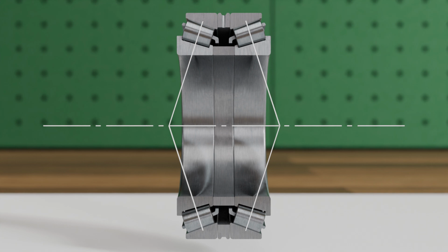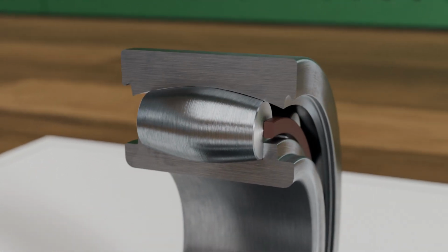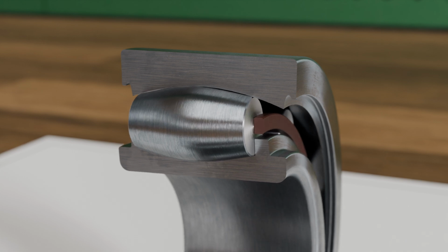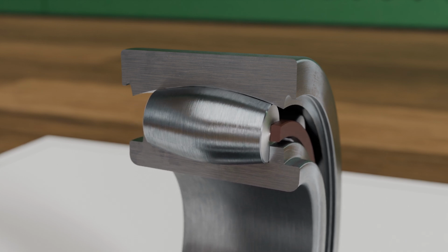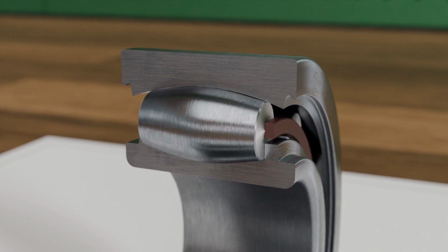To combine the high load capacity of the line contact of the rolling elements with the ability to compensate for angular errors or shaft bending, spherical roller bearings with barrel-shaped rolling elements are used. These spherical roller bearings, also called self-aligning roller bearings, have a spherical outer ring raceway that combines high radial load capacity with the ability to compensate for misalignment up to 3 degrees. This makes them especially suitable for applications with dynamic loads and possible misalignment, such as heavy vibration-prone or oscillating machines or systems with elastically supported shafts.